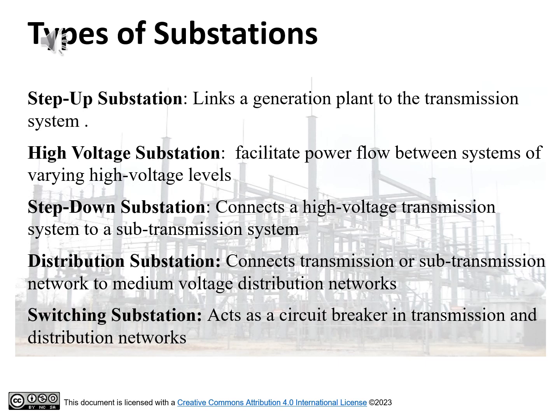A step-up substation links a generation plant to the transmission system. A high voltage substation facilitates power flow between systems of varying high voltage levels. A step-down substation connects a high voltage transmission system to a sub-transmission system.